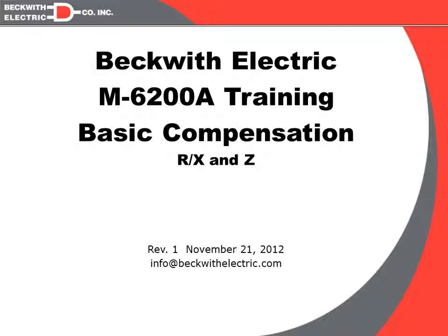This particular session will be on line drop compensation, and it'll have two parts. Part one will be the basic settings, which are R, X, and Z. In part two, we will be discussing other compensation methods such as VAR biasing and remote voltage biasing.